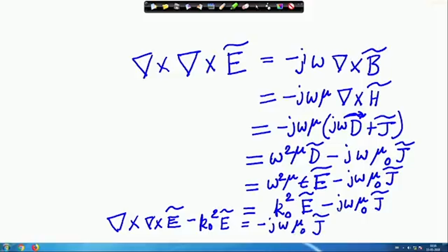So, this is amenable for solution, because you see the left hand side is the unknown E and the right hand side is the known source quantity, that is the current density that the structure is supporting. Others are all constants, I know. So, I can theoretically solve this. So, antenna analysis is from this, and once I know E, I can put that into Maxwell's equation and find H. So, the whole of antenna engineering could have been solved by this.